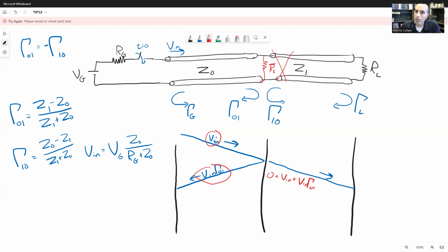In this case, it's as if we have a resistor, except its value is Z1. So the second transmission line almost acts as if it were a load, except instead of having the voltage simply jump up on a resistor, that becomes the value of a new wave that is launched into the second transmission line. So let's quantify that and write it down. All right, we're going to go back to this case right here.